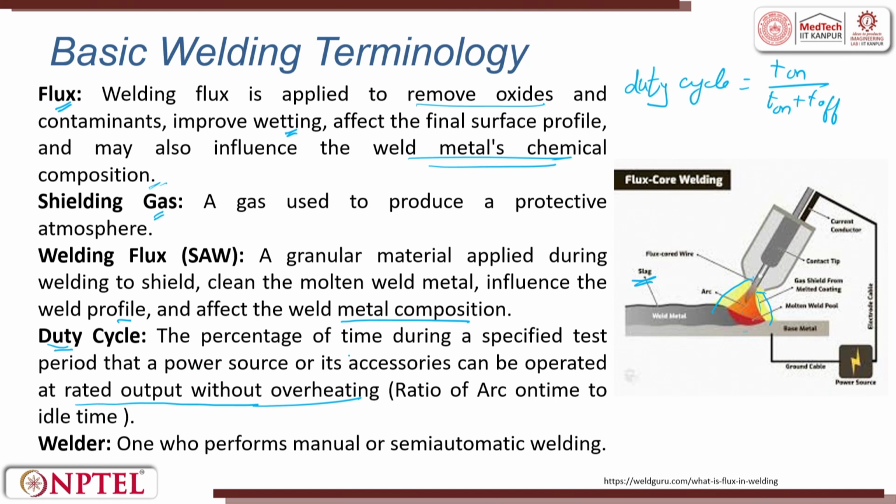So, the percentage of time during a specified test period that a power source or its accessories can be operated at rated output without overheating is called the duty cycle. It is the ratio of arc on time to idle time. This is what I said, duty cycle. So, this is also very important.